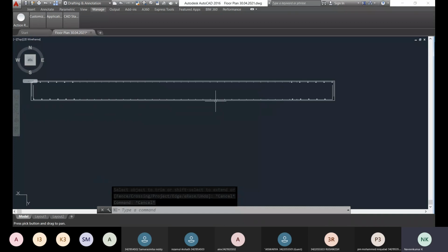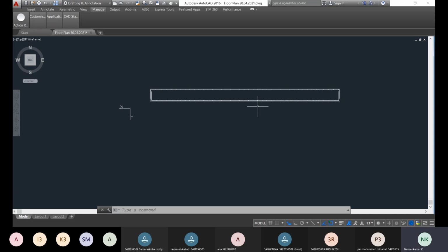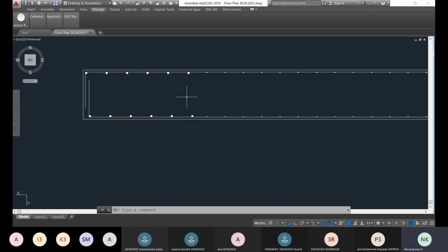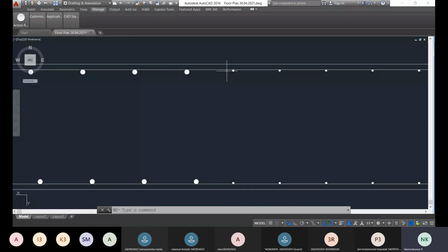We have created the main reinforcement as well as the distribution reinforcement for the solid slab of the bridge, which has been designed as per the recommendations. So we have given the reinforcement detailing. Next, you should provide the crank. If you see here the transition, from the 25 it transited to 15, so this portion has to be cranked to take care of the shear, like a separation only.